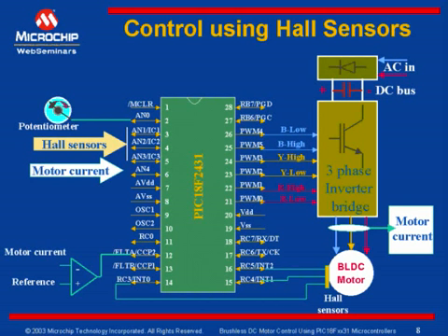So optionally, with this, timer 5 can be captured on each transition. This timer 5 value can be used for determining the speed at which motor is running. This gives a low resolution speed measurement. Using timer 5, we can determine at what speed the motor is running, and this gives a low resolution speed measurement using Hall sensors.